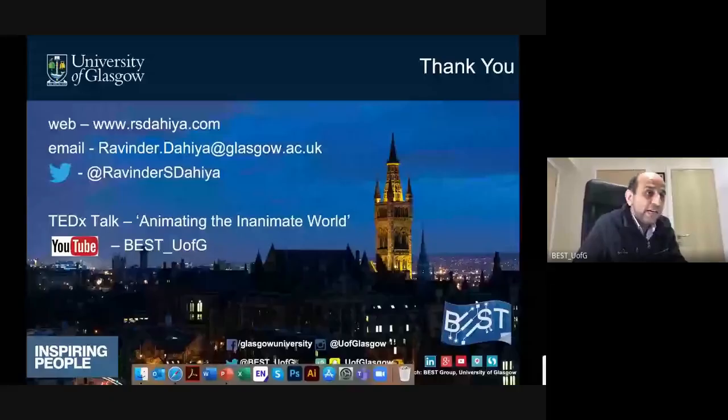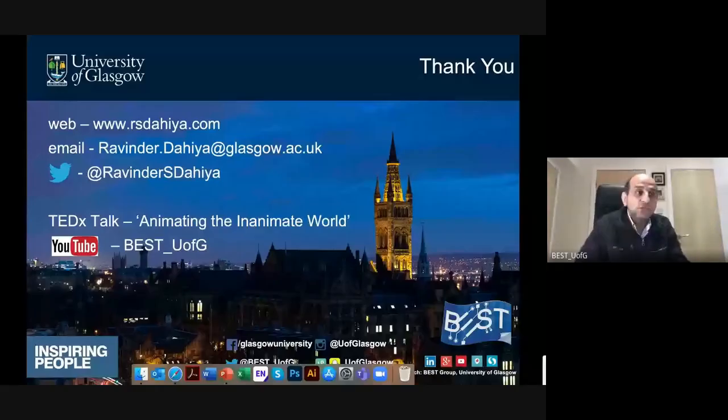But you can also use metal foils if you go to high temperatures, and you can still then use the printed electronics. So with metal foils, you deposit some dielectric on that, and then you can use that as a substrate. It would still be flexible. You have to think about how the temperature itself would change the performance of electronics. Perhaps by using other materials, not silicon or zinc oxide, but materials that are currently used to develop electronics for harsh environments, we could explore that. We have not looked into this aspect at this point.